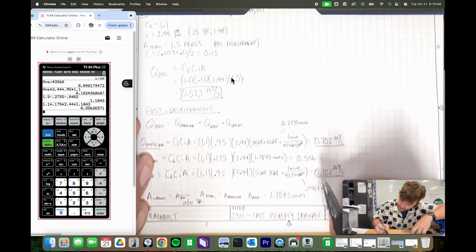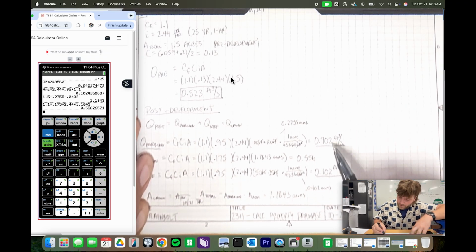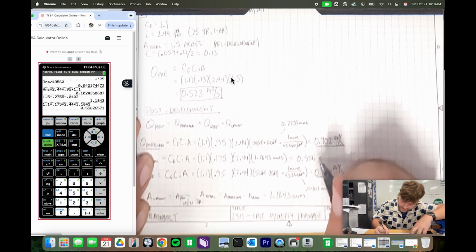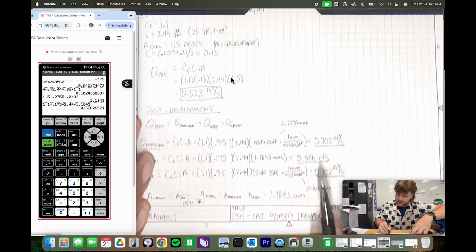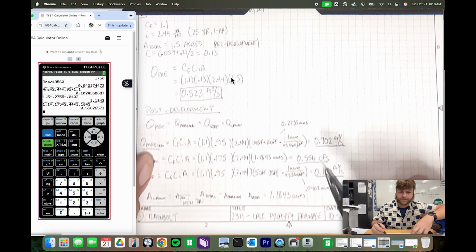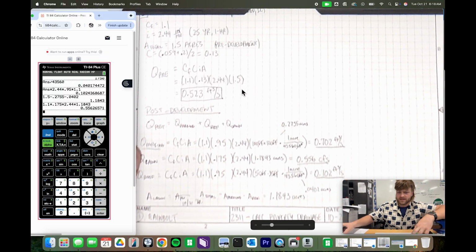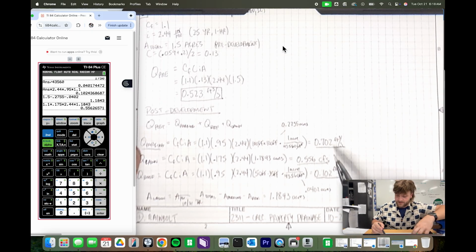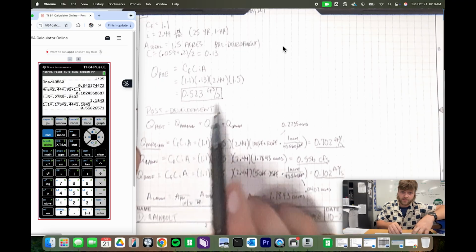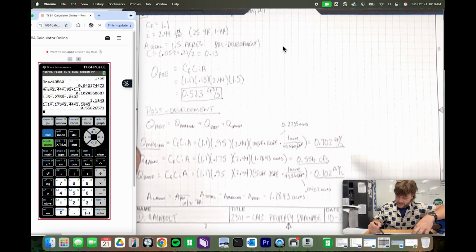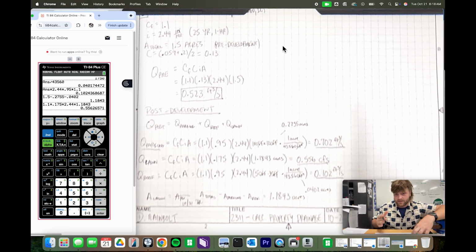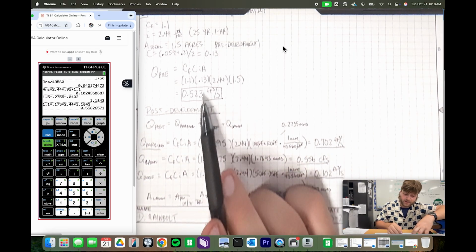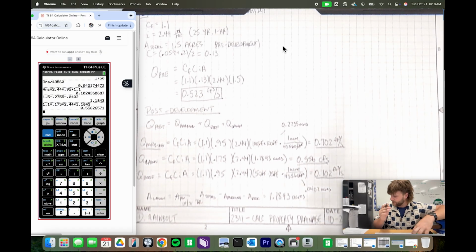And so now we've got 0.556, and then we'll call it there just because we went to the thousandths place for all these other values. And then for this one, just to show you guys, you can also use that unit, CFS. It's the same thing. It's just cubic feet per second. And so now we ended up finding out this post-development here. And as you can imagine, this is a pretty big value, especially in comparison to what our Q pre value was up here. It's 0.523. Just from the lawn alone, we've actually got 0.556 cubic feet per second, which already has exceeded our Q pre.